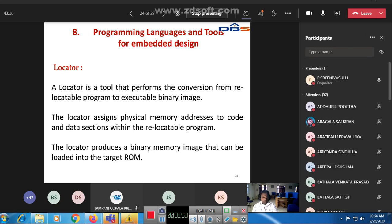A locator is a tool that performs the conversion from a relocatable program to an executable binary image. So what will this locator do? The locator assigns physical memory addresses to code and data sections within the relocatable program. Before the locator we have a linker. The linker will create a single object file. Then that object file is given to the locator. The locator will relocate that entire object file into different memory locations, like program memory and data memory, so that the locator assigns physical memory addresses to the code and data instructions.